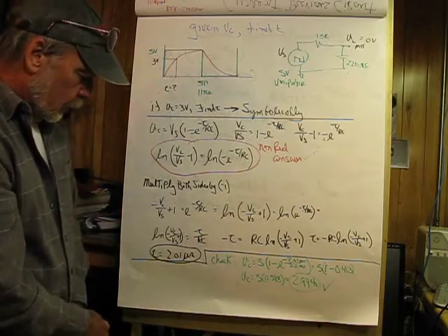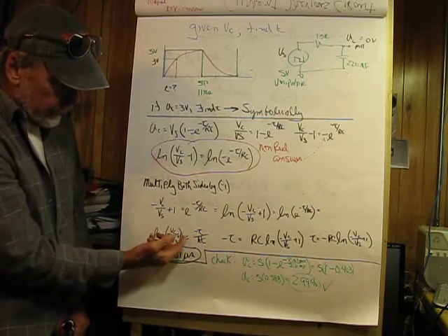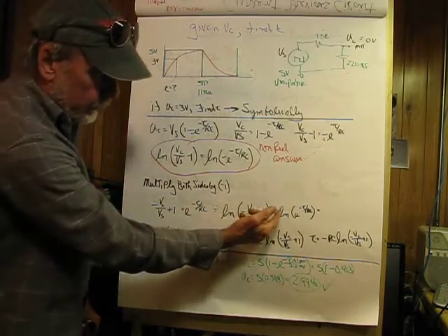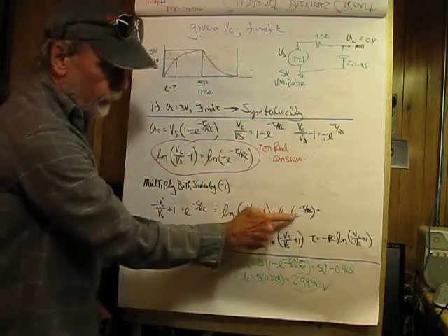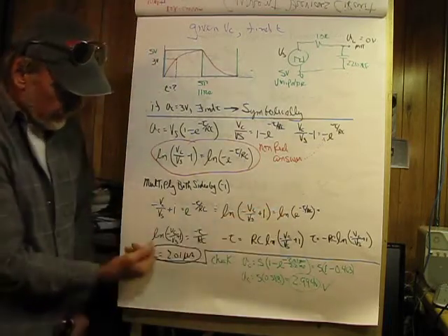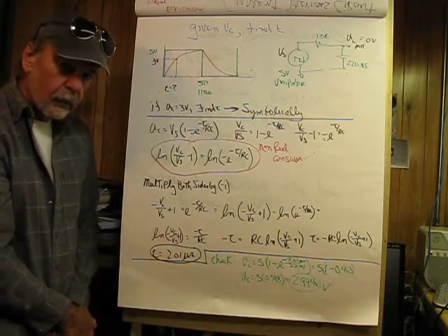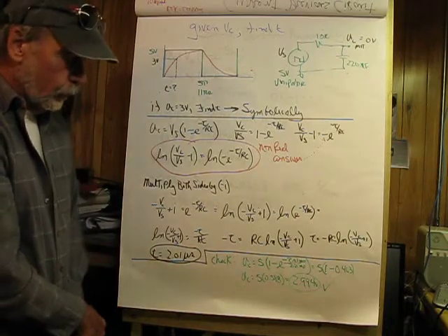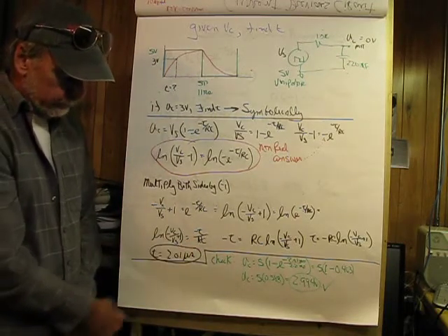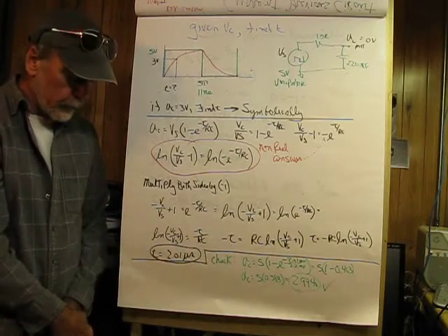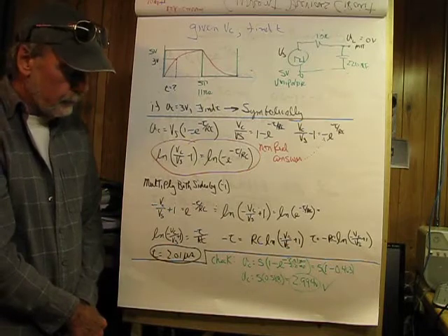So we have the natural log of this quantity, and since we did this, essentially taking the inverse operation gets rid of the e, we end up with this is equal to negative t over RC. So we're really close to solving this now. All we have to do is get t by itself, and we'll do that by multiplying both sides of the equation by RC.